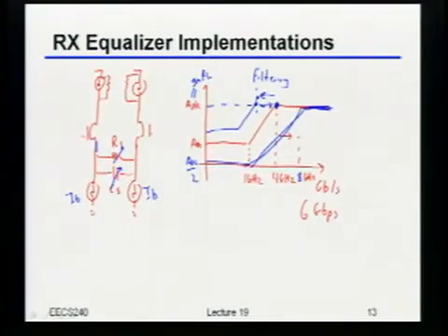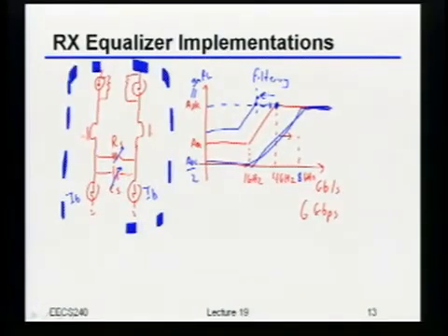What'd you say, Dan? 2 amplifiers. Yeah, I could just take this whole thing and repeat it, right? I can just add another stage afterwards. And then I have 2 independent zeros I can create. Now, that works, and indeed oftentimes may actually be the right answer. But let's say that I really just want a very slight additional amount of peaking, or I don't want to spend any extra power at all. Okay, I still want 2 zeros, but I don't want to spend any extra power.